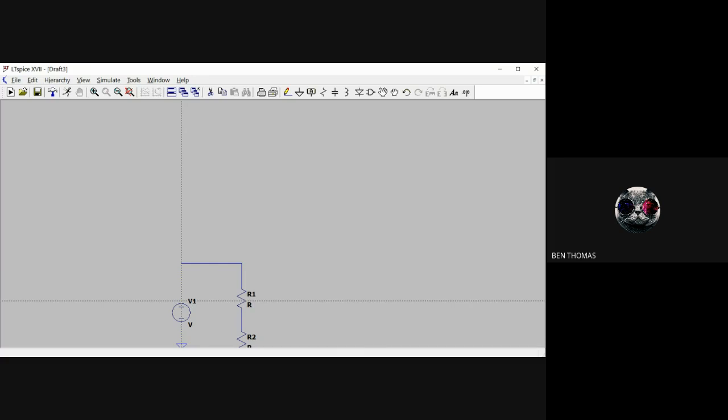A square icon will be there, close to the voltage. Click there, and after that, wherever you want, click and move it in any direction, north, west, south, or east. After you reach the destination, just left click again, and a wire will be there. When you are done, just right click.